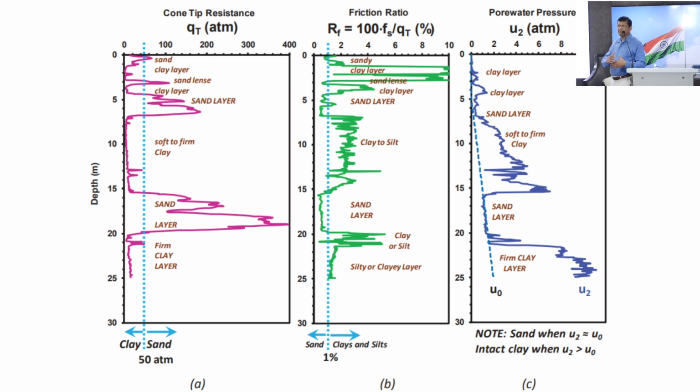If you have seen what the effect of groundwater is during a seismic event, you see the groundwater rises. There will be a big rise in the groundwater and the pore pressure also increases during the seismic event. That kind of seismic event is generated when we are driving a cone. That's how we get what we call the dynamic pore pressure.